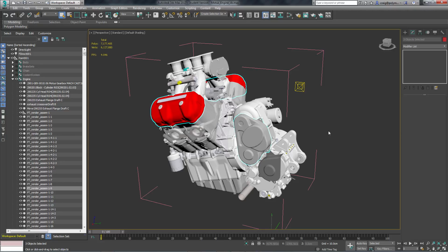But if we need to do some fixes, maybe you need to repair the geometry or address the decimation on the geometry or fix a UV map, for example, and you need one part to come back. If you've sent everything as one giant FBX file and you need to fix one part, you could get into issues back and forth with things like losing the positional data on an FBX file. And of course, exporting everything one by one can be quite time consuming as well.